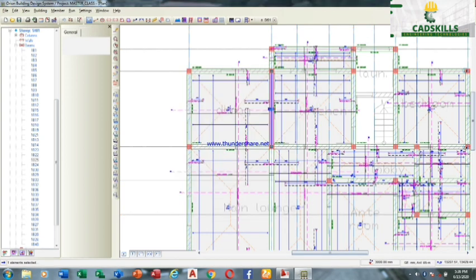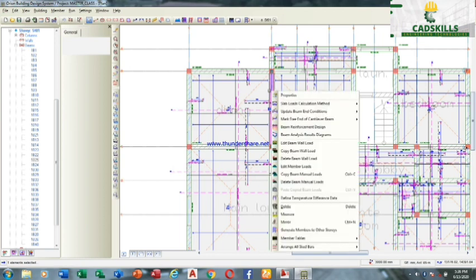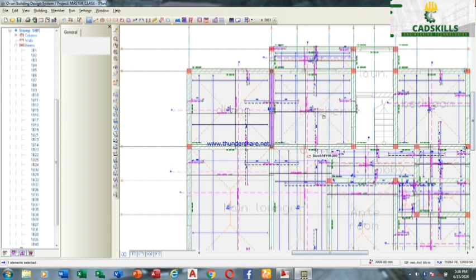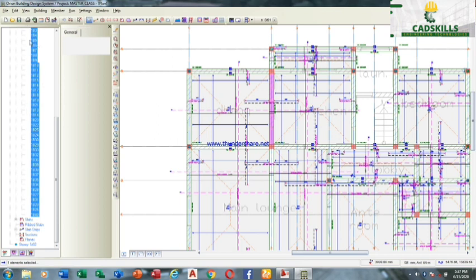Right, you click OK. As you click OK, right click, copy beam wall load. You want to copy this load to all these beam walls. So as you copy it, click this first one, go down, hold shift key down, and click the last one. It will highlight all of them and begin to highlight them inside the drawing. Your mouse remains triangular, but when it finishes, your mouse will change to square. So let's watch it and see when it finishes. All right, it has finished highlighting them.